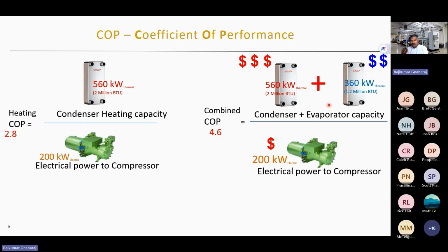Same for steam boiler. If a steam boiler is 80% efficiency, that steam is utilized to heat water. When you burn fuel in the steam boiler, the efficiency of the hot water system could be like 80%. Like if you burn $1 worth of natural gas in the boiler, you're going to get only 80 cents worth of heating. Whereas in a heat pump, you use 1 kilowatt of electricity, you will get 2.8 kilowatt of heating and 1.8 kilowatt of cooling.